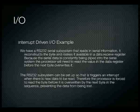To give you an example of that, we have an RS-232 serial subsystem that reads in serial information. It reconstructs the byte and makes it available in a data receive register. So simply, we have data being pumped down to our processor in a serial fashion. The shift register is reconstructing it at the right rate. So after 8 serial shifts, we've got an 8-bit value that's pumped out to a data receive register.